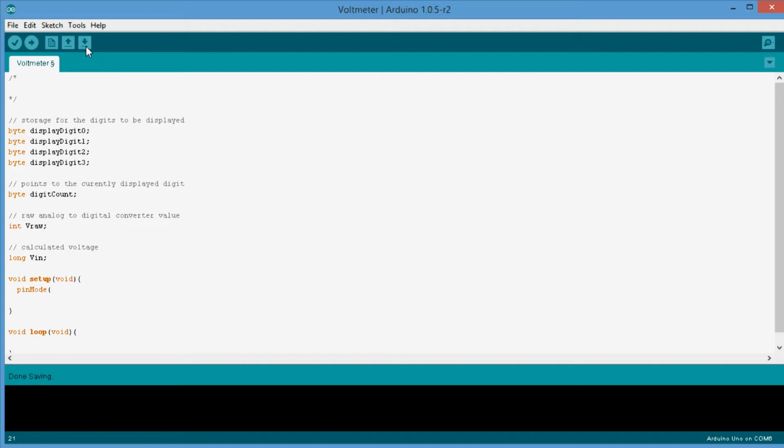The first one is the pin number that you want to work on, so we'll start with 0. And then a word that defines what state the pin should be, either an input or an output. In this case, we're going to make it an output, so I just write OUTPUT, all in capital letters. It has to be in capital letters. Now this has to be followed by a semicolon as well. So now we've just set up pin 0 only as an output. I want to do all of the pins that way.